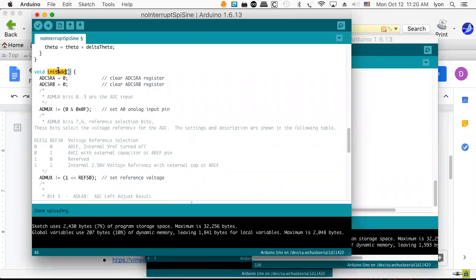I used this init ADC to gain access directly to registers. And so we had reviewed what happens when we start to manipulate these ADC status registers at the bit level. And so what I wanted to do was kind of point out some nice ways in which you can set up your code to make it a little bit more readable. And so I worked kind of hard making this as readable as I could possibly make it. You can have up to 16 A to D inputs depending upon which Arduino you're at. So there's the least significant 4 bits available in the ADMUX.